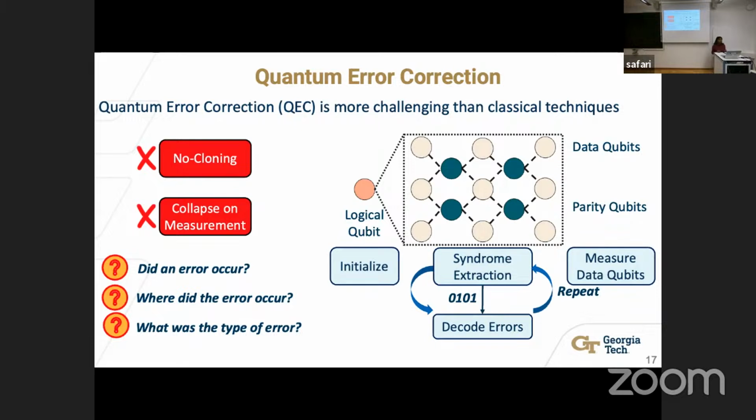So what is the runtime requirement for different devices, let's say, in terms of seconds? So yes, for superconducting devices, like the surface code study we did, we looked at the syndrome extraction time. That's the fastest you can get your syndrome. So you want to correct it as soon as you can get your next syndrome, because else you will have uncorrectable faults. So that's about 1 microsecond. There are future predictions. For example, in the next work I'll talk about, there are predictions that you want to do this at a much faster rate, something like 400 nanoseconds.